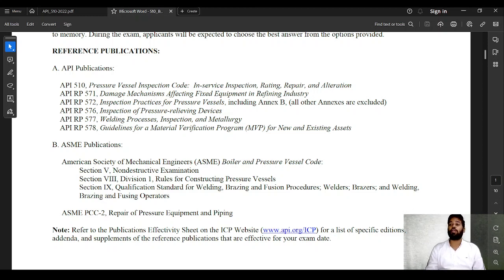effective enough? So what are the things to be understood while you are performing a welding operation? What are some documents that are needed? What are some non-destructive examinations that can help you to identify if the weld is correct or not? All of these requirements are given in API 577. So it's a recommendation given to the inspector so that they can perform welding operations correctly.